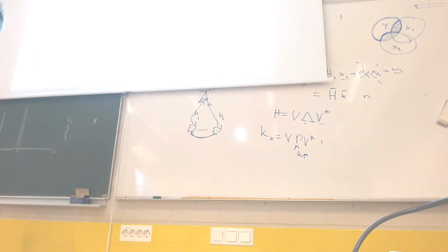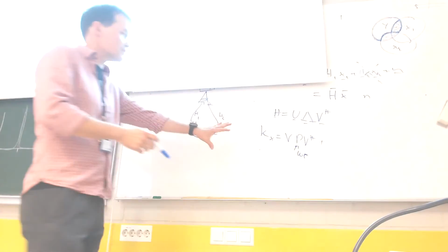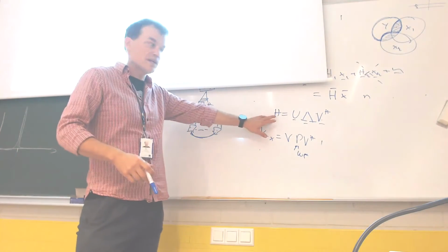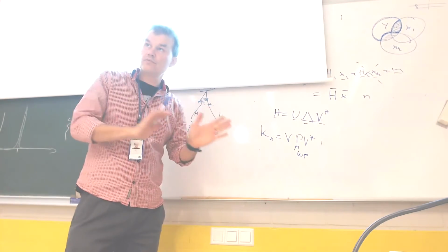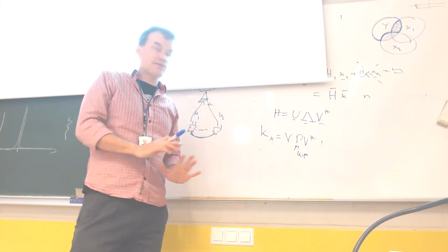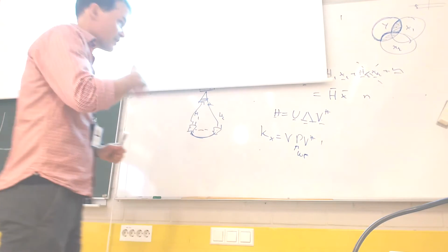You can do this also for a multi-user case. You can optimize them individually, but it's suboptimal. It's really suboptimal. You will see this. This could actually be one special case. So for both users, you can do SVD and then construct Kx, assuming the other user is not there. You can still use that Kx for both users, but it's suboptimal from a sum-rate perspective.